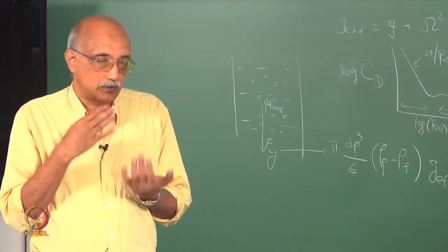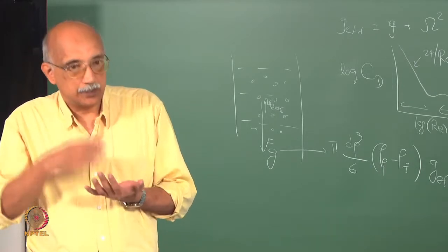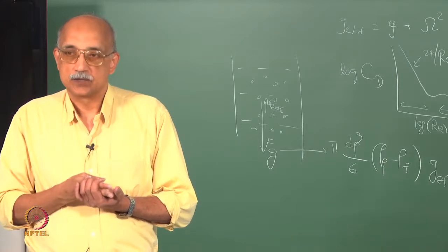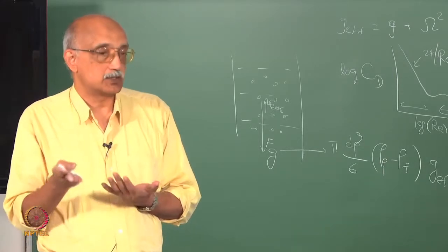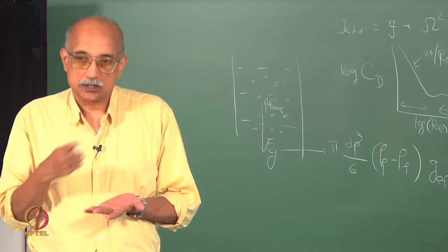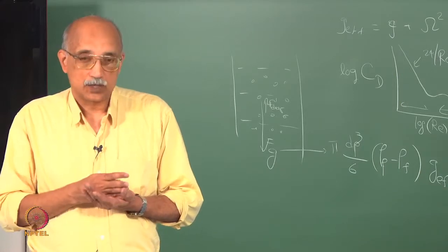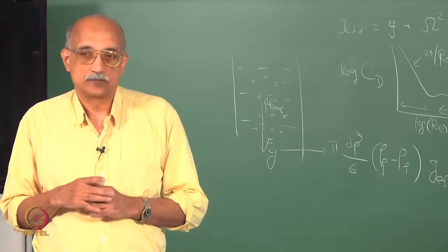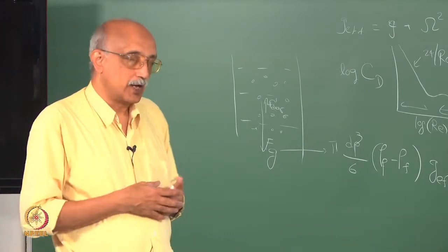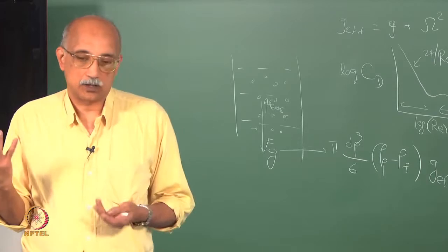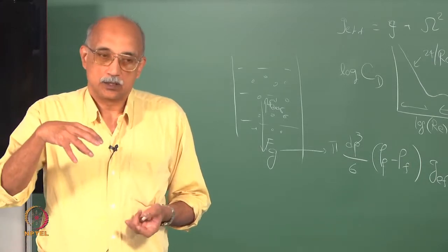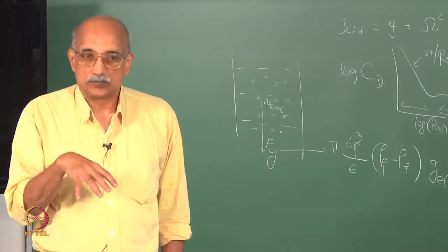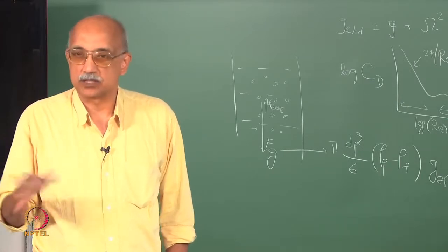As you go from micron to submicron, there is a clear increase in the settling time. However, when you go from submicron to nano, the difference in the settling time is much smaller, and once you reach nano dimensions, the settling time is virtually independent of size. Intuitively, it is obvious: if you have nanoparticles suspended in a fluid, they are not going to want to settle, they are going to want to float basically.